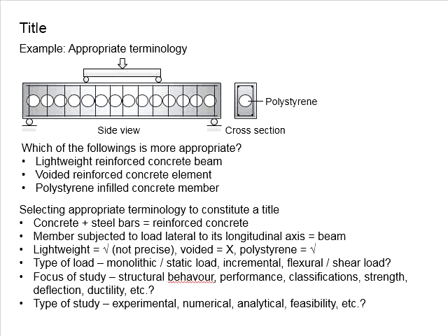Next, we look at the type of loading. What kind of load do you apply onto the member? Is it going to be a static load or a dynamic load? The difference between the static load and the dynamic load is whether the load remains constant, placed at stationary conditions, while the dynamic refers to a moving load or fluctuating loads.